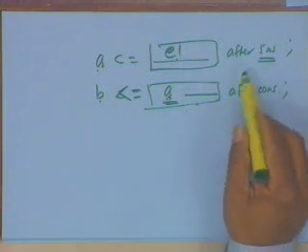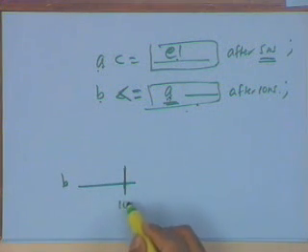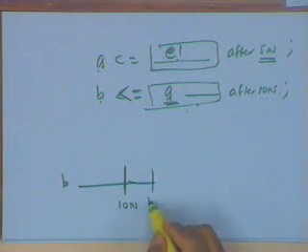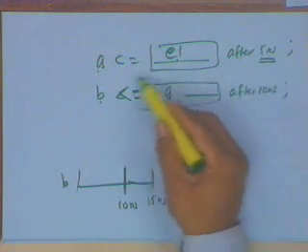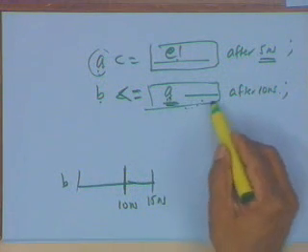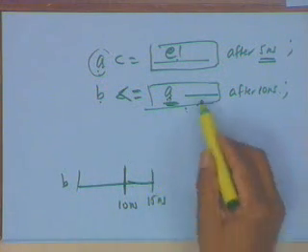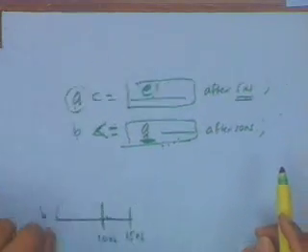So if you look at the value of B, there could be a change after 10 nanoseconds and there could be another change after 15 nanoseconds from the current time, because after 5 nanoseconds this A value changes, it will re-trigger this, and the new value may be the same or different, and that will be assigned to it after 10 nanoseconds.